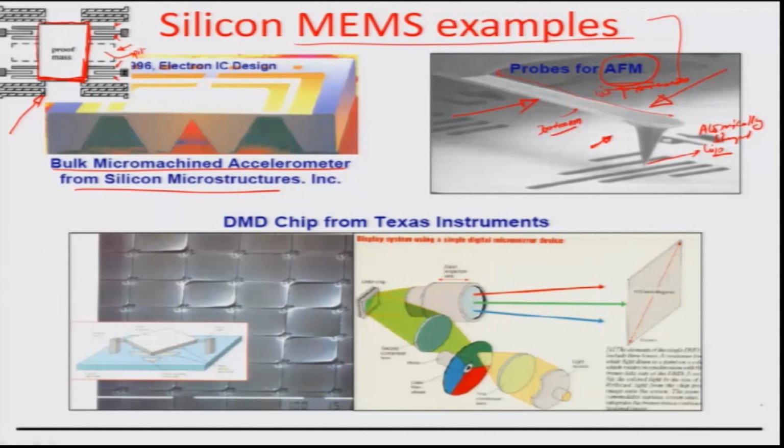And on the base which is this particular area, the pit is what is illustrated by these vertical lines, and the inclined lines show the base. So, there are different structures which are carved on the base. For example, there is a structure which is an electrode like this, there is another electrode, and again a third and a fourth electrode in these two regions right here. So, the idea is that the proof mass is positioned in a manner with these extended wings, you can say, of the proof mass, that as the proof mass twists and turns based on the overall motion of whatever system is carrying this small unit or this small chip.